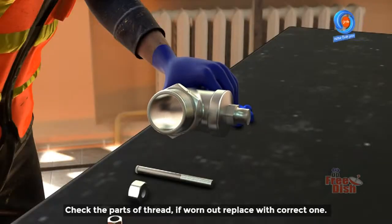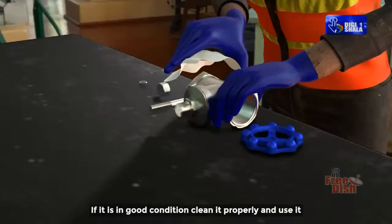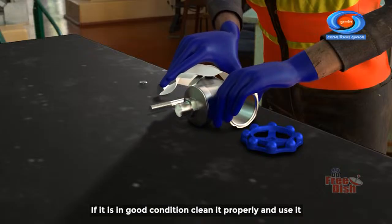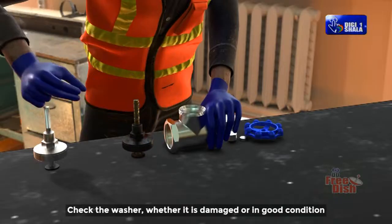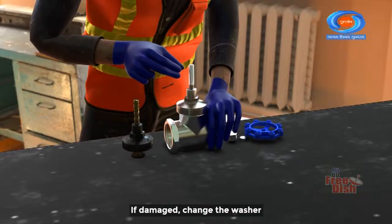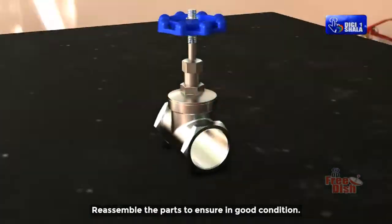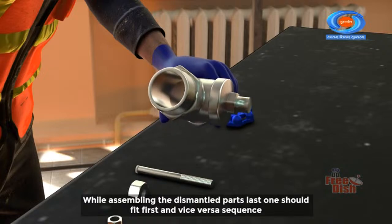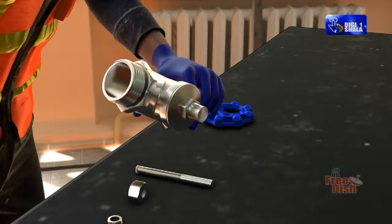Check the parts of thread. If worn out, replace with the correct one. If it is in good condition, clean it properly and use it. Check the washer, whether it is damaged or in good condition. If damaged, change the washer. Reassemble the parts to ensure they are in good condition. While assembling the dismantled parts, the last one removed should be fitted first, in reverse sequence.